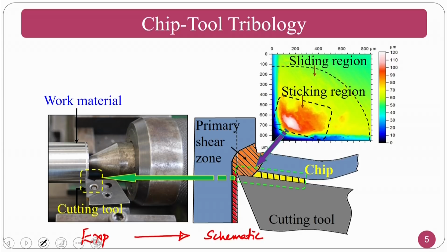If you zoom into this area, we have a sticking region, and here it represents the height of deposition that is taking place. The red and white colors you see at this position stand for the peaks, or the height that is forming. Assume that this is my surface, and see how things are piling up on top of it. Built-up edge formation and all these things are studied there. This green region has slightly less height. Beneath the chip, the material is adhered to the tool material.